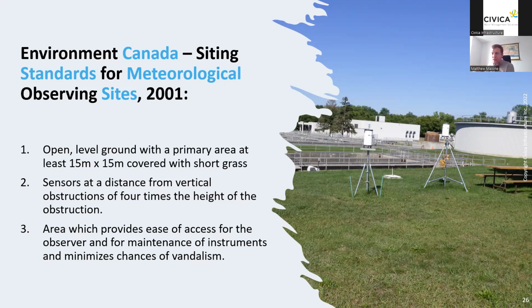different levels of accuracy and setups that you can go to get the highest level of accuracy, having things like wind baffles, and various ways to set it up to get to certain quality levels of rainfall data. But in general, you want it to be open, no obstructions, easy access, try and minimize chances of vandalism, things like that. You can get bird guards, so you can stick them on top so birds don't sit on it and cause you issues. But these are some of the high level recommendations and ways that you want to set up a rain gauge.